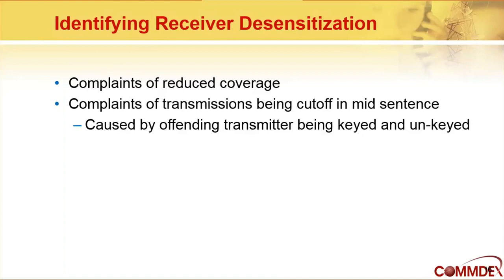And that's great if it's a high-powered broadcast transmitter, but oftentimes it's going to be some intermittent transmitter that you have to be lucky enough to hear when it happens. So you may have to place some equipment on site and walk away and let the equipment listen for it to happen. It may only happen once or twice in a 24-hour period, but just enough that the user gets annoyed by it. So it takes patience to track down interference, and we're all patient people.